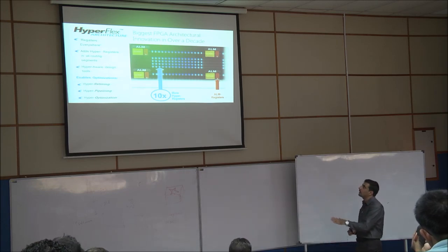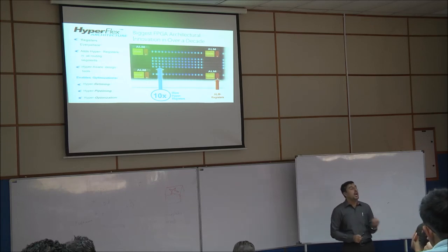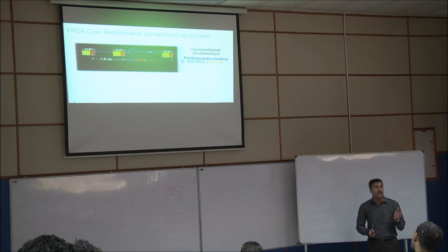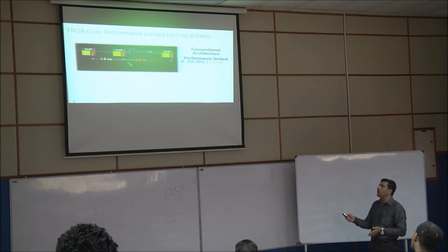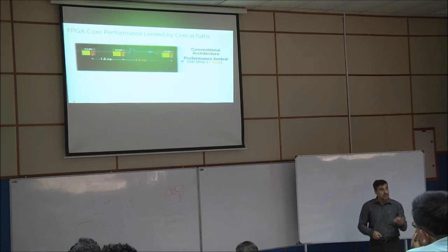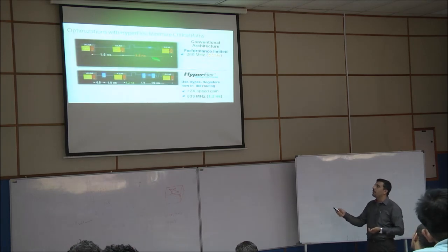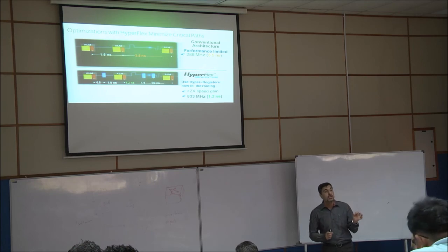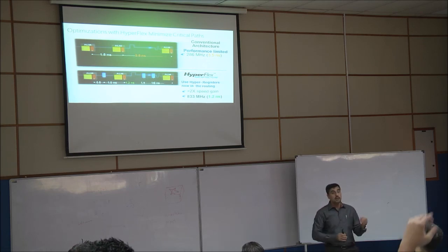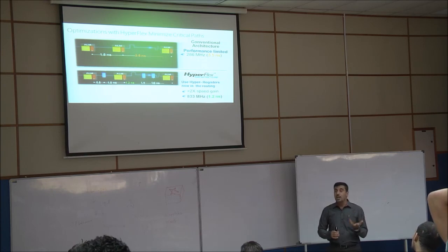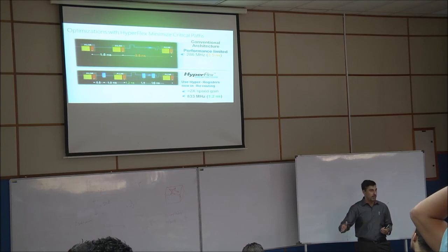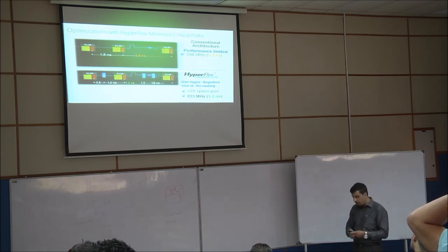Now in FPGA, with the HyperFlex technology or architecture, the register is faster than the routing itself. So I'll show you here. You see between two ALMs, ALM means adaptive logic module, we have a 3.5 nanosecond delay, just routing, just wire, inside the chip. After we add the HyperFlex, the maximum for one register is 1.2 nano. Clear? So now the delay in the register is less than the delay in the routing itself. This HyperFlex technology increases the speed of processing inside the FPGA, so the Lattice 10 becomes faster and faster. Clear? So this is what I want to highlight in this hardware.